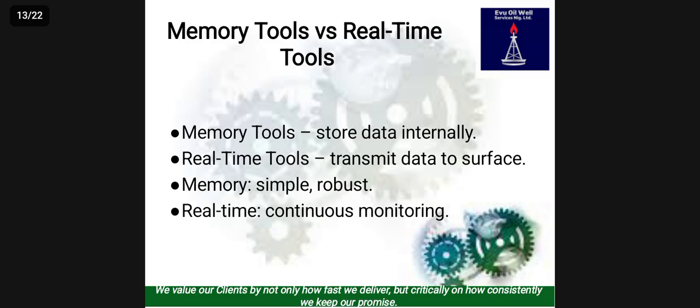Memory tools versus real-time tools. Memory tools store data internally, and the advantage of a memory tool is this: it's simple and durable. The real-time tools send data instantly to surface. Immediate feedback is the advantage.